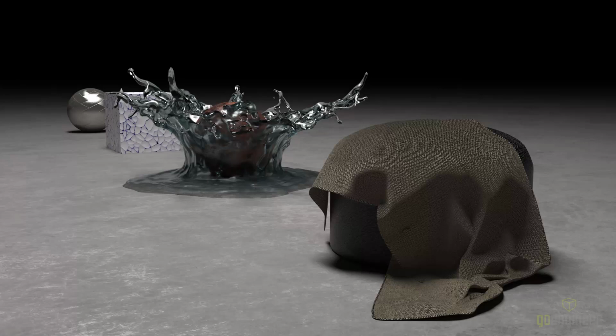My resolution is 300 pixels per inch. The number of render passes that I chose is 5,000. And my render selection mode is set to accurate mode, which allows me to utilize path tracing, which is just going to give me a little bit more accurate results in the end when I'm creating my render.